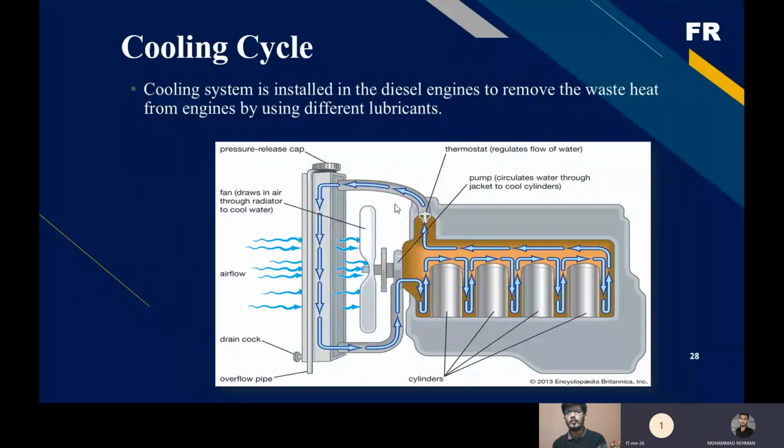Now, let's come to the cooling cycle. First of all, we will see why cooling is necessary in the diesel engine. The diesel engine works on compression; it is a compression ignition engine. The compression process inside the engine produces so much heat. We need to reduce that heat because the heat generated is so high that it is higher than the melting temperature of the metal from which the parts are manufactured.